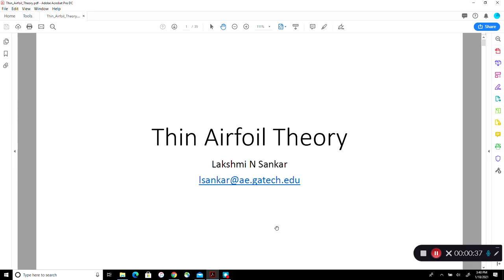So in this section, we extend it to something closer to our heart, which is airfoil aerodynamics. Airfoils can be modeled exactly. That means applying the boundary conditions directly on the body surface. This is called the thick airfoil theory, or so-called panel method. This is what is used in many programs, including Xfoil. We will cover panel method in a later video. But today we are going to start with a very simplified version of it called the thin airfoil theory.